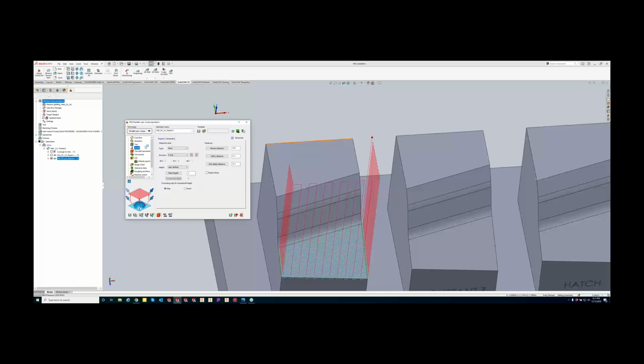Now, usually when we've been covering profile and pocket, machining levels is basically how deep we want to go. Levels here is all about your clearance. Now, toolpath parameters. If you think about toolpath parameters, think of the step over as how pretty of a finish you are looking for, or what kind of surface callout we are looking for in there.